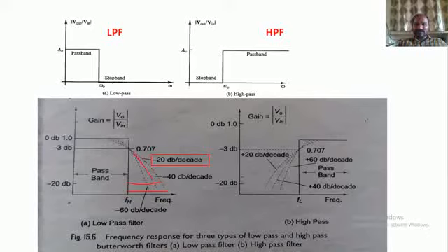We will see the second order low pass filter circuit diagram also. Don't worry about it. But as there is an explanation on this particular graph, I would like to cover all the things. Okay, now when you take the second order low pass filter, this is the second order low pass filter response. Now if you see this, in the first order case it is accepting so many components, but when you increase the order, it accepts fewer frequency components after the cutoff frequency. Okay, so the gain we are having is reduced. This is the gain response. This gain is reduced very fast compared to the first order.